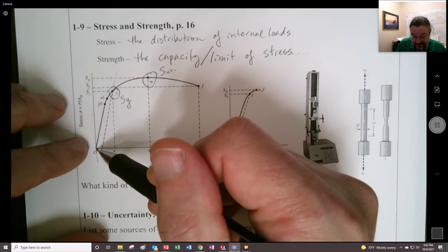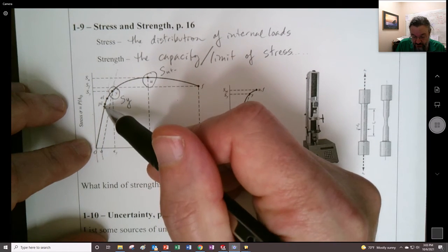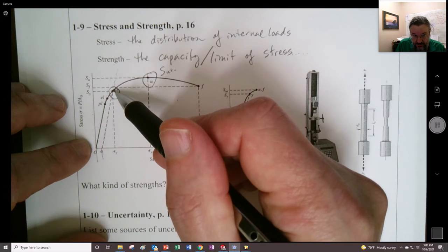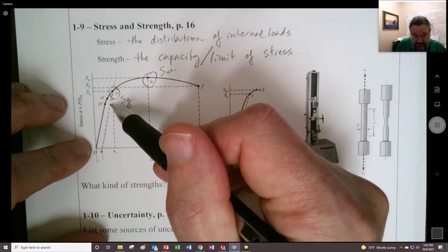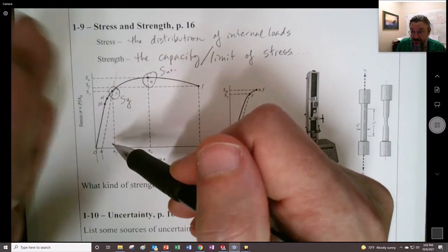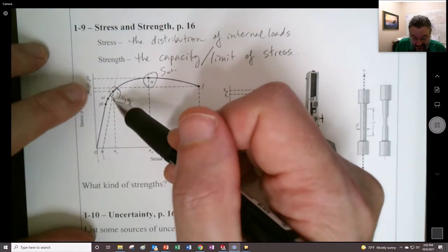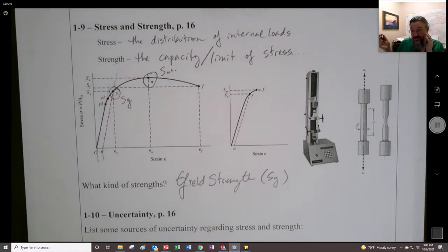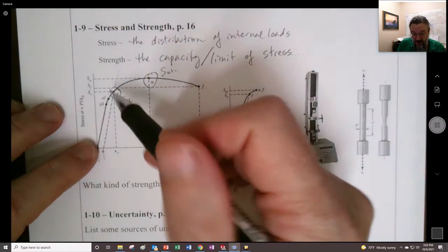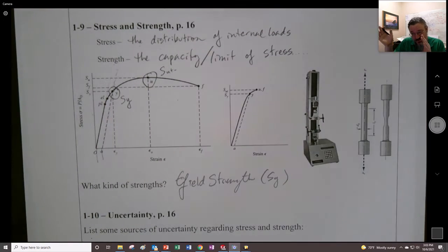In fact, interestingly enough, it's going to climb up this curve as you apply load. It's going to get here, and you release the load. It's actually going to come down in a different path, parallel. It's interesting, isn't it? Anyway, it's going to have some strain that doesn't go away. Usually it's going to come up, and maybe it'll rebound a little bit, but it's going to come back, and it's not going to get to the original size that it was.